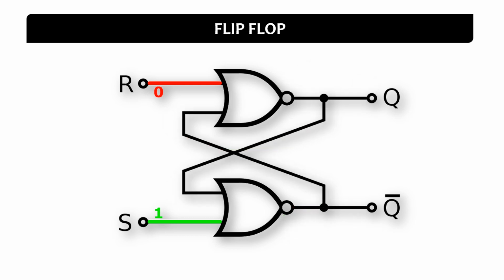So what is happening over here is that this circuit contains two gates, and two different phases. It is just like on off. We can consider the example of our normal switch, which has a set and reset, meaning on off every time. When I say it's a set phase or a set status of the switch, it means the next phase will always be the reset. Or if I say the current state is on, it means the next phase is definitely going to be the off state. So this is a simple switch type of concept, also we call it a latch.